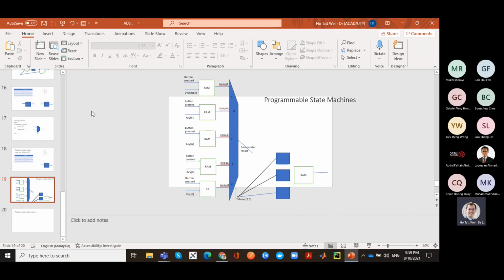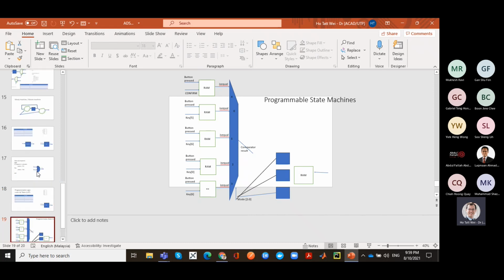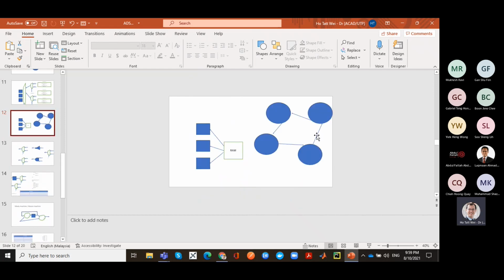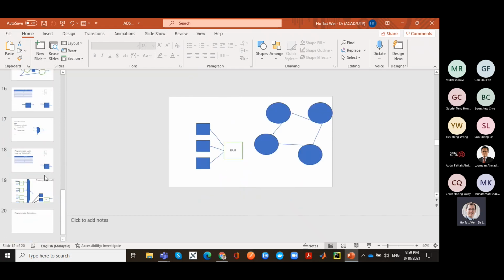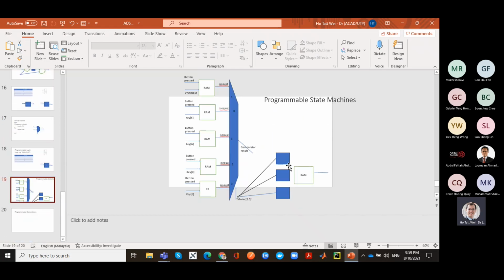If you encode one particular state transition, then it's not programmable. It's a fixed state machine. But what makes a microprocessor flexible is that you can implement different kinds of state machines by writing different instructions, a different sequence of code. That's your program. A program is nothing else but a sequence of instructions, and a sequence of instructions is nothing else but a sequence of modes and the data to operate on. And a sequence of modes is nothing else but a sequence of states.